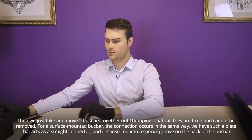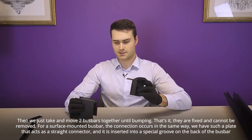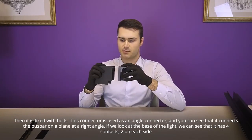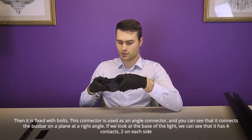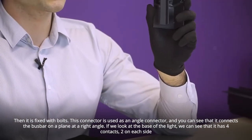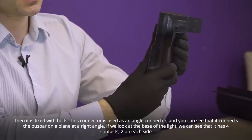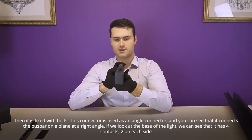For a surface-mounted busbar, the connection occurs in the same way. We have such a plate that acts as a straight connector, and it is inserted into a special groove on the back of the busbar. Then it is fixed with bolts. This connector is used as an angle connector, and you can see that it connects the busbar on a plane at a right angle.